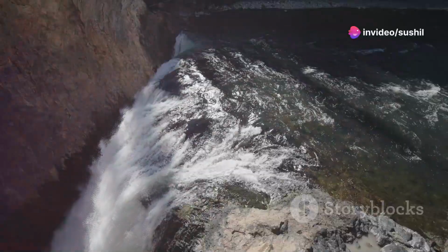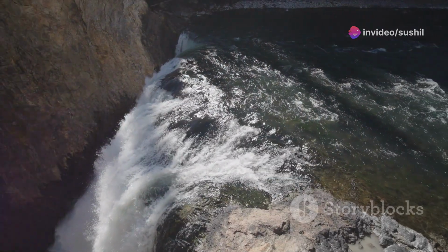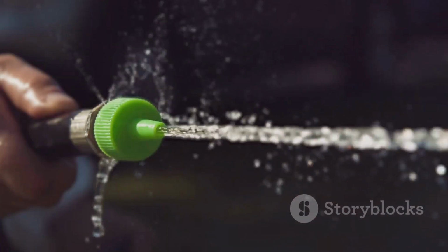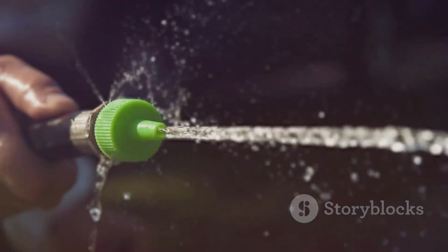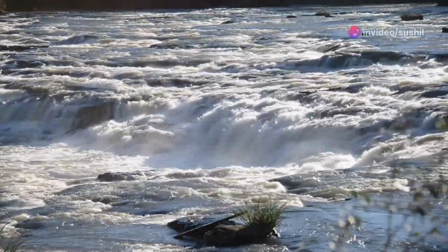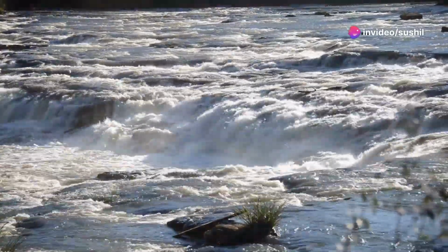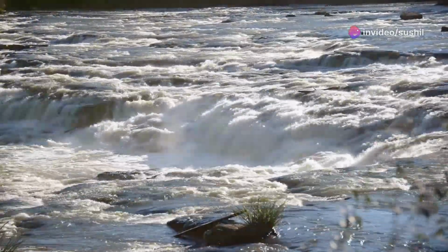As the fast-flowing water enters the wider section, its velocity decreases. Bernoulli's theorem tells us that this decrease in velocity corresponds to an increase in pressure. This higher pressure downstream pushes back against the incoming flow, causing the water to pile up and create a sudden increase in depth, the hydraulic jump.